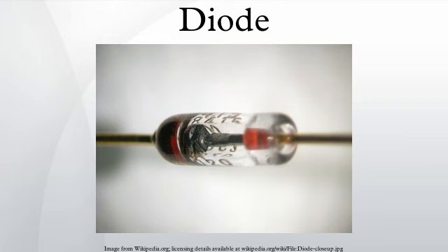The alternating voltage to be rectified is applied between the cathode and the concentric plate electrode. When the plate has a positive voltage with respect to the cathode, it electrostatically attracts the electrons from the cathode, so a current of electrons flows through the tube from cathode to plate. However, when the polarity is reversed and the plate has a negative voltage, no current flows, because the cathode electrons are not attracted to it. The unheated plate does not emit any electrons itself. So current can only flow through the tube in one direction, from cathode to plate.